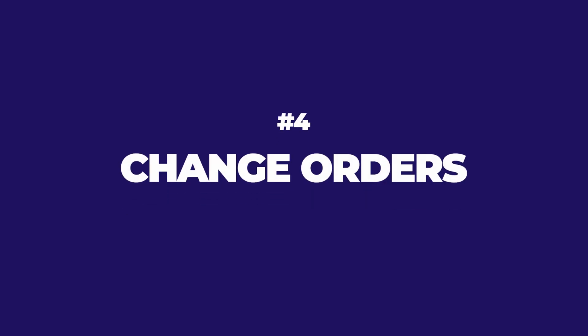So let's talk about number 4, change orders. Once we have a design, we have a plan, we have a schedule, we know how we're going to build this project, we now have established a GMP. Now, if something changes after that, that will be covered under a change order. That change order can increase the amount in the guaranteed maximum price or the GMP, and it can extend the schedule, but typically, instead of doing that, the owner and the contractor will partner and take it out of contingency within the budget and within that overall guaranteed maximum price.